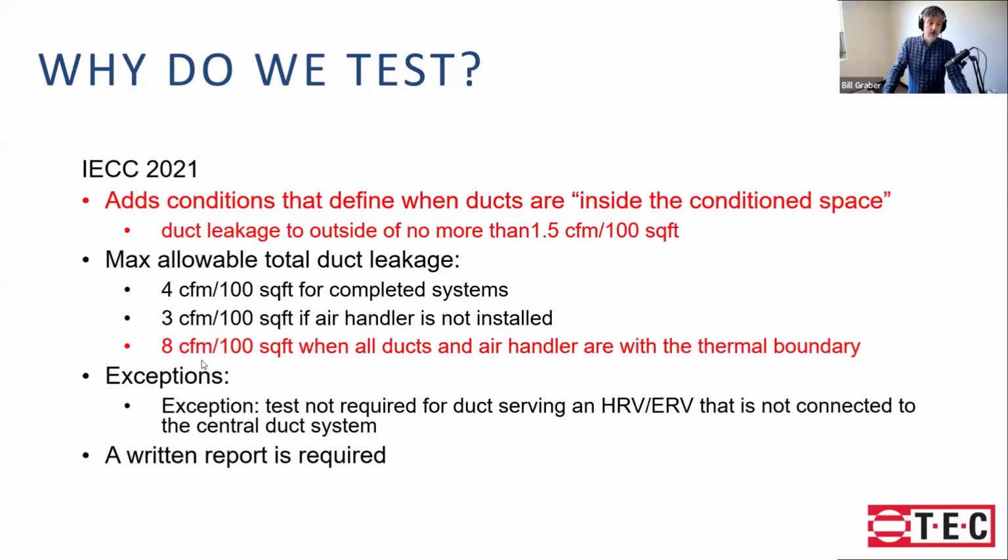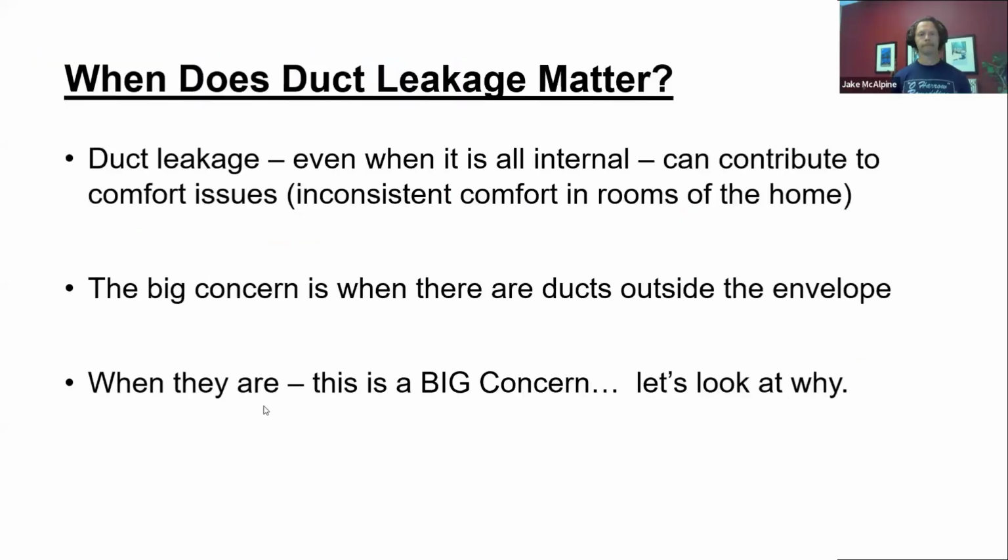Yeah. Okay. So even when they're all inside, you got to test them, and there's a metric there, and then duct leakage to outside specifically called out. So these are some changes. We're seeing more and more people calling and doing the testing because of these changes and this new code being adopted in some of the states already. Yeah. So that's really helpful.